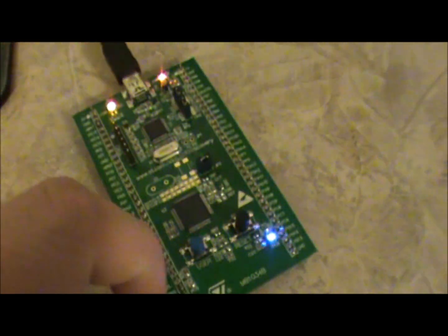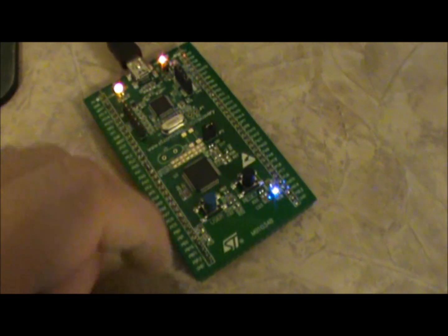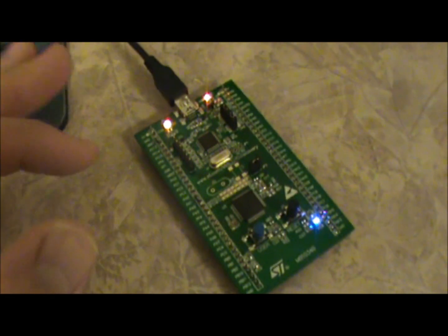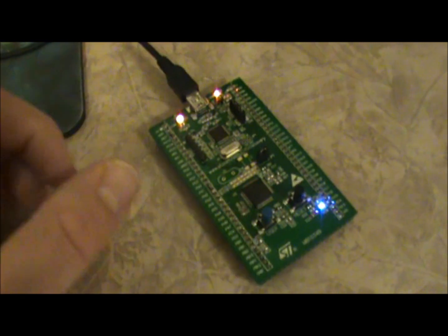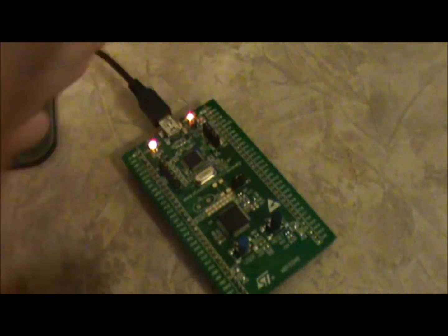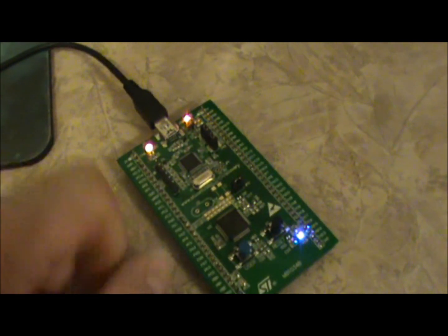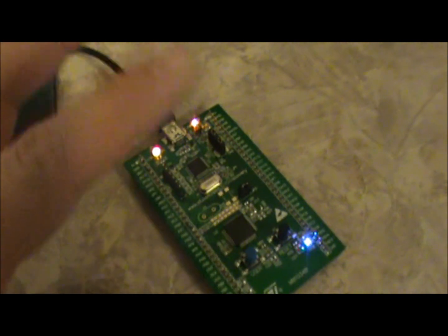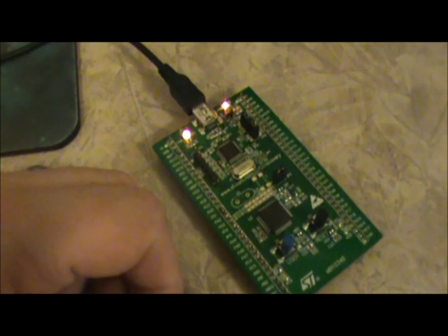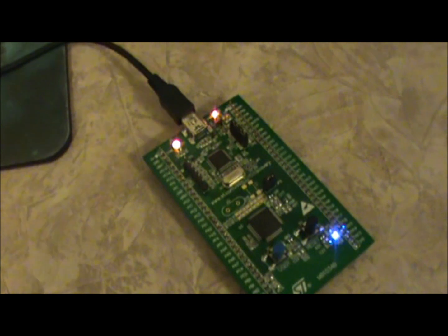And that's pretty much it, guys. Got our little blinky deal to work. I could play with it, except using my left hand when I'm right-handed doesn't work very well on the mouse. Otherwise, I would show you how you can change the timing and get it to blink faster or slower, or whatever you want to do. But that's pretty much all there is to it. It's really simple. Connect it up, let Windows install its drivers, then pull up your ST-Link utility and open up your hex file, and go from there.